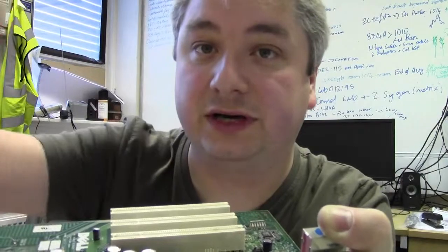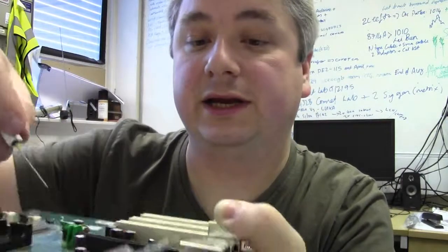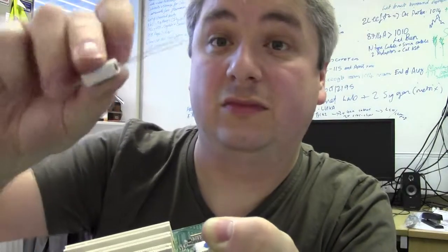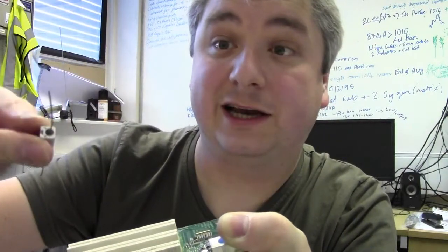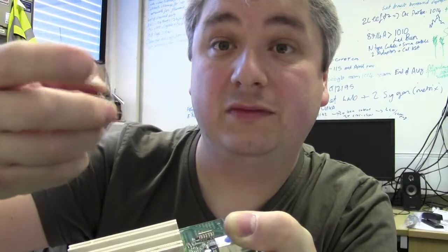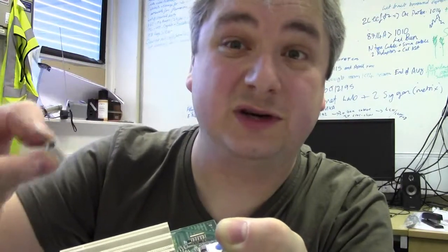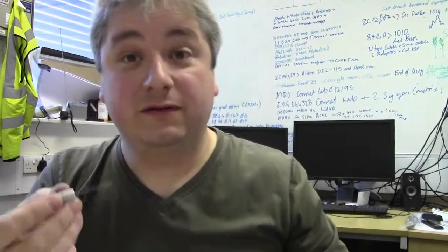I mean, it's no good buying a 10 ohm resistor that's gone, and buying a 10 ohm wire one because it was dirt cheap, or you had it lying about. Your wire is about 1 millimetre thick, and it may not go through a hole because your hole's only 0.8 millimetres wide. So you have to be very, very good at making observations and deducing which one it is.